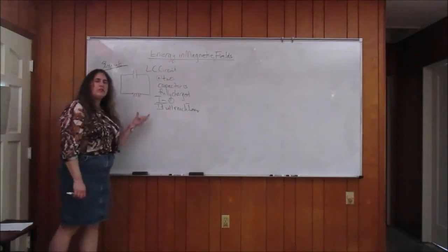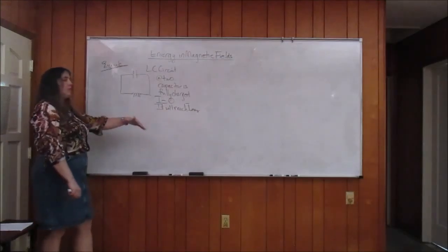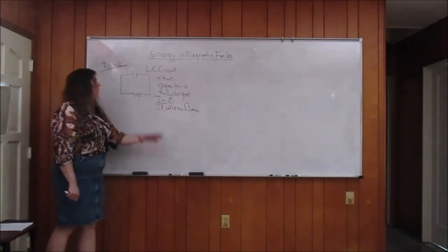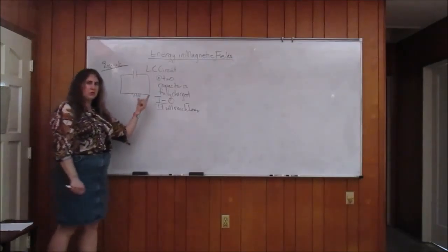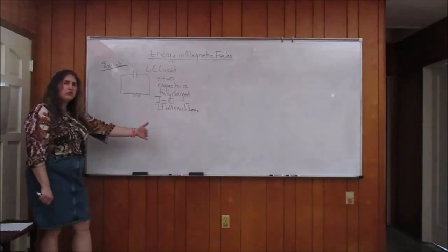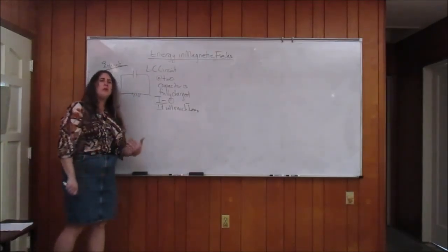So once it reaches its maximum value, it can't again change instantaneously. It's going to persist. So the capacitor is going to start charging once again. But again, your rate of current flow is changing. So the magnetic field changes, the magnetic flux changes, there's an EMF induced that opposes that change.